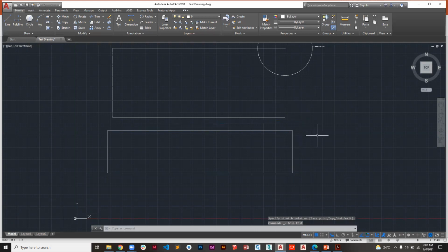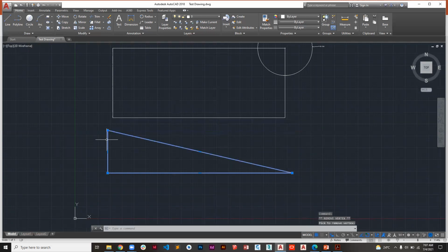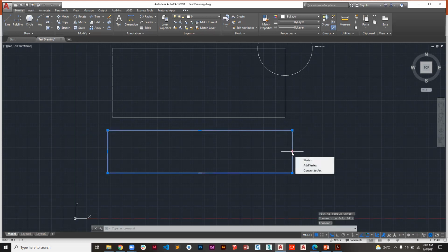Yeah. Then another one is about removing. If I remove, it's going to turn into a triangle because now I've removed that edge. Then when we come to these ones in the middle, you can convert that particular line into an arc. Then you choose the middle point of the arc. So if it is this, then now this is how you end up with this shape.